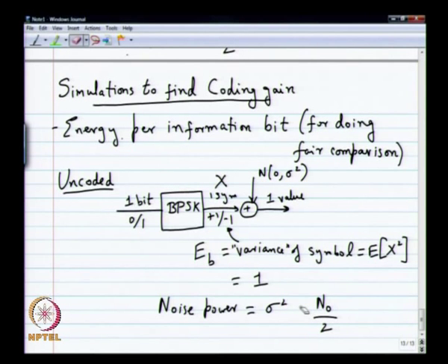The white noise that you expect in your receiver will be controlled by this N0, and if you do your receiver right, if you do orthogonal projections or match filtering carefully, you will get a noise of N0 by 2. That's for the variance. This is just some kind of digital communication. Once again, we do not have time to go into these details here. So I'm assuming you're doing either the course now or you've done it before and you know that this is true.